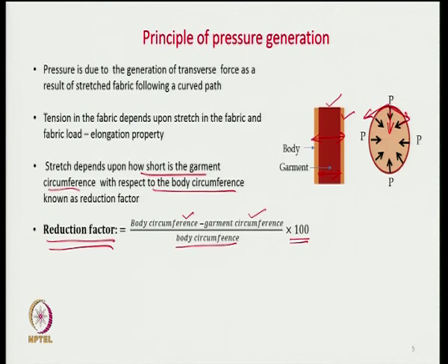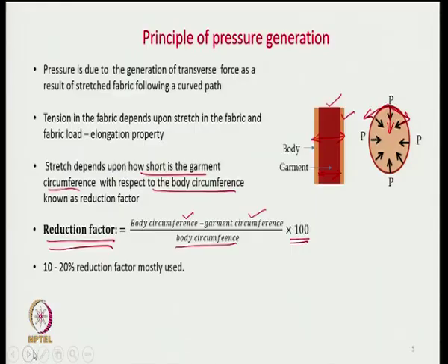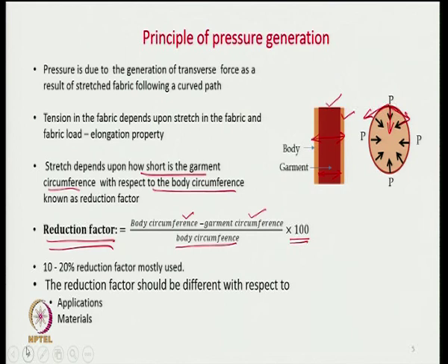So, that means whatever pressure garments we have, they will always be a little shorter than the body part over which they will be resting. Typically, the reduction factors are 10 to 20%. The reduction factor should be different with respect to applications and the material that you use. Obviously, ultimately what matters is a certain amount of force we have to generate, and the force is a function of the stretch of the fabric.